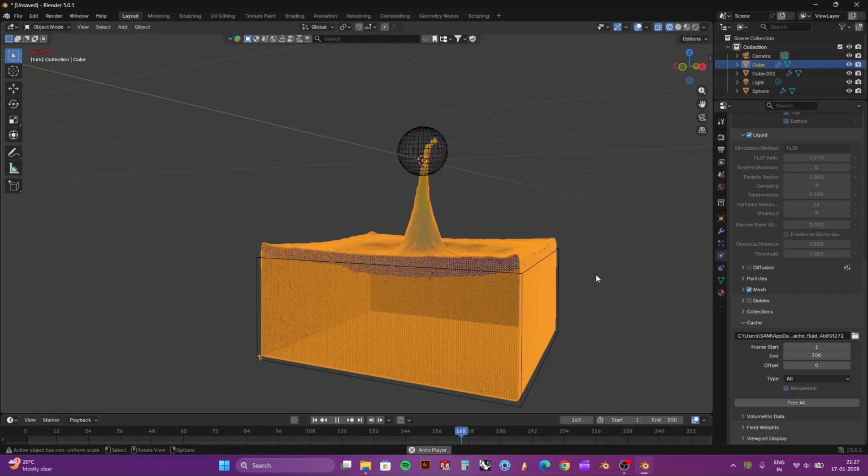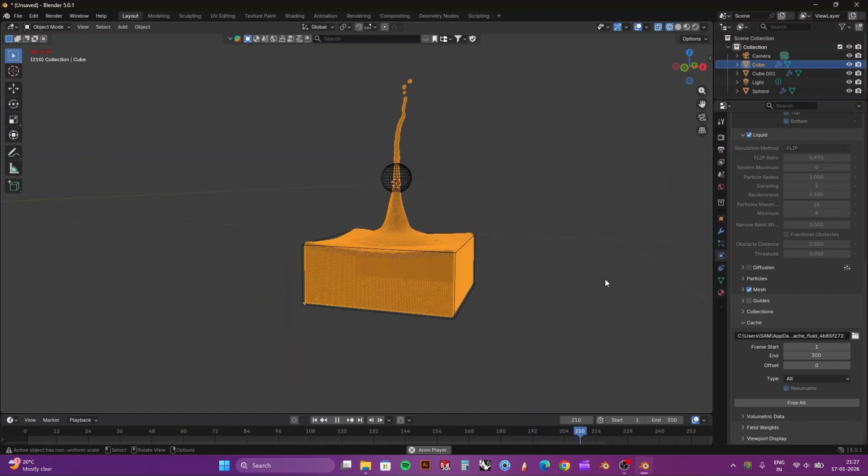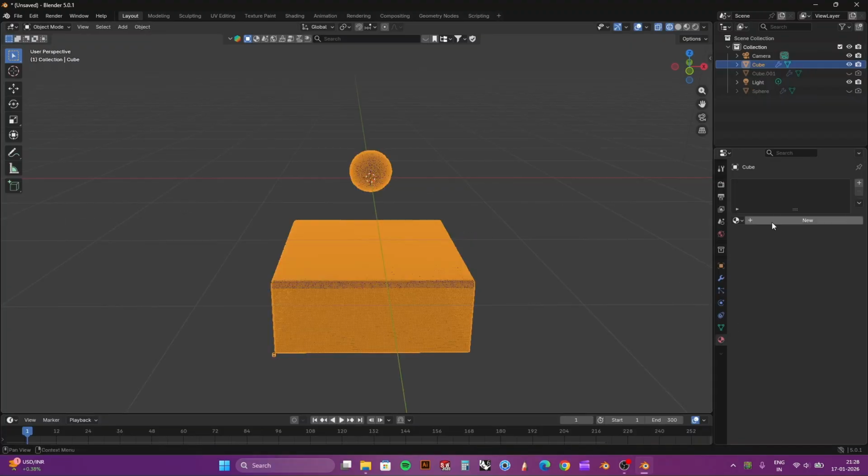Just make sure the time scale which you are choosing should not be 1. It should be less than 0.5 or 0.4. Then you will get a very good slow motion water simulation. And also CFL number should be lesser than 2.